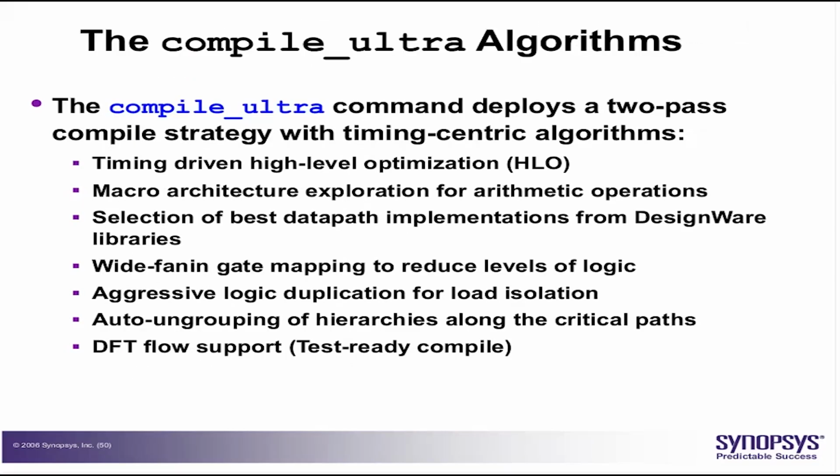Right? So now let's discuss briefly about compile ultra. How does it operate? Compile ultra by default is a two pass compile. That means inside, when you run a single compile ultra, there are two levels of compile happening.